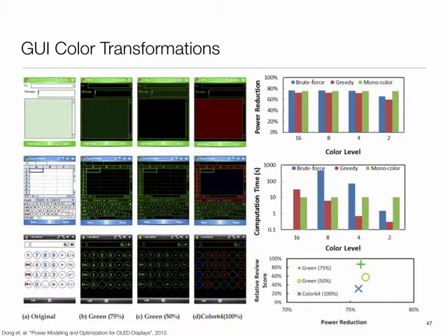What else? Number of frames a second. In case of video, that would be an issue, because that's stressing the GPU. What else? Maybe use half the screen, something like that, right? You can go to a reduced effective screen size and literally turn off those pixels. With OLEDs, it would work easily. With LCDs, you will need a segmented backlight to make that happen. So these are some of the things that one could potentially play with.